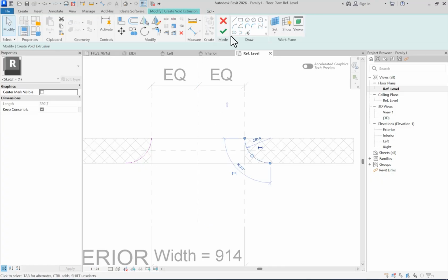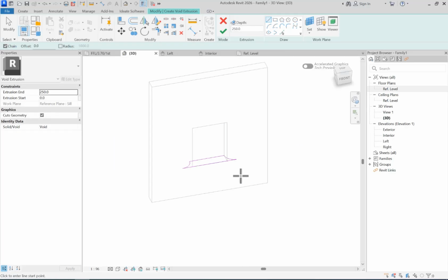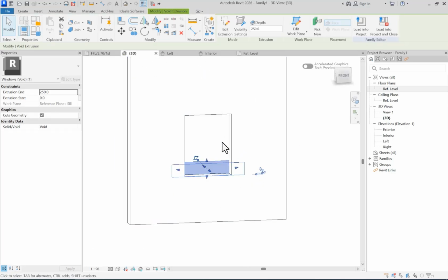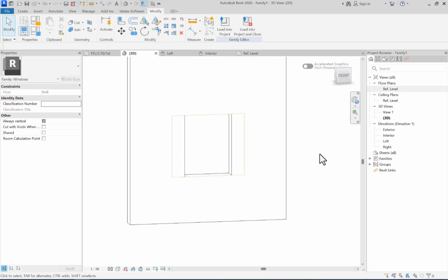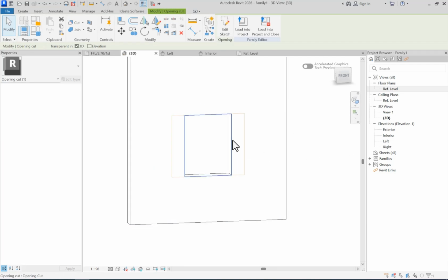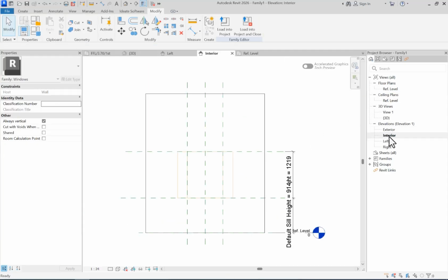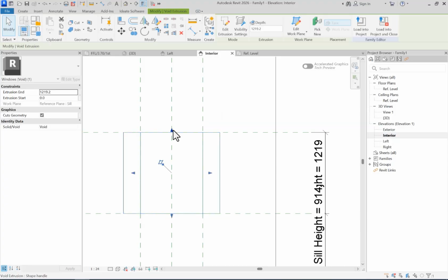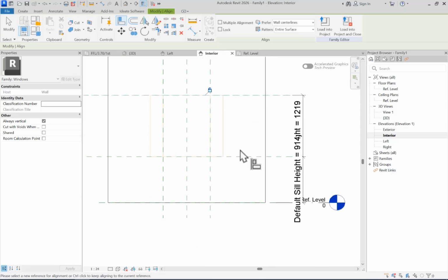See, guys, you just need to know how to use an item. The techniques and tricks are quite simple, honestly. All right, now after hitting finish, I can go back here, select this, and move it upwards. Now, remember, guys, we can't complete the cut here just yet, not unless we actually remove the opening that we had before. And also, guys, before cutting anything, first we actually need to lock this with our reference planes. Why? Because I want to make sure that the window is going to work parametrically.